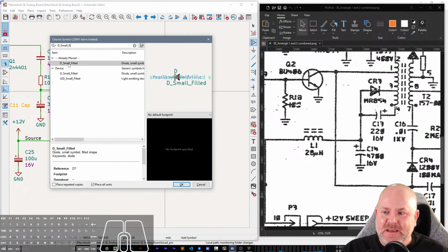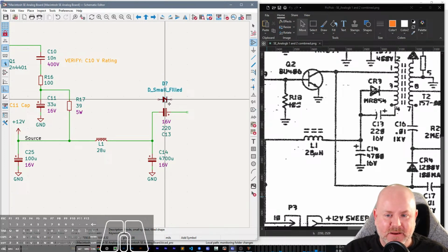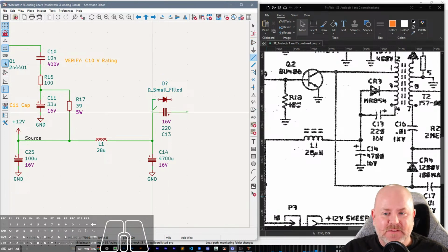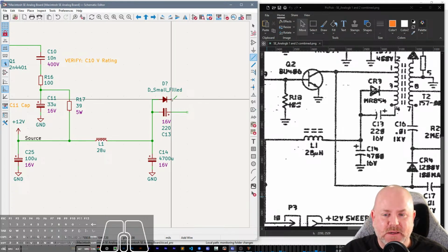Pretty much at this point, the 2 buffers I like are the 245 because it's bidirectional. So even if you don't need it to be bidirectional, it's like, okay, it works fine. And then the 573, although that's a transparent latch. And then there's one other one that I want to find. I'm trying to think why the transparent latch I don't like.